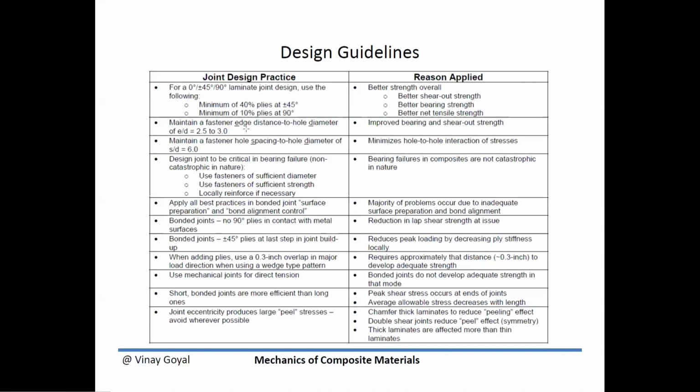Use mechanical joints for direct tension. Bonded joints do not really develop adequate strength in that mode, so it's important to really use mechanical joints for those conditions, if you can. Short bonded joints are more efficient than long ones.